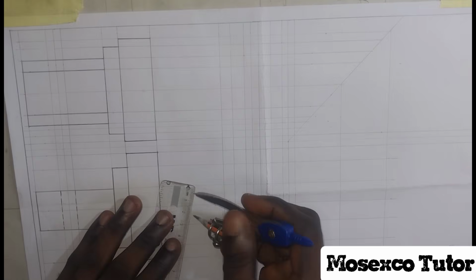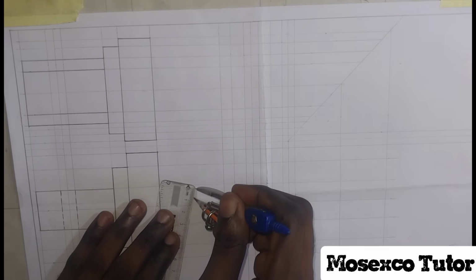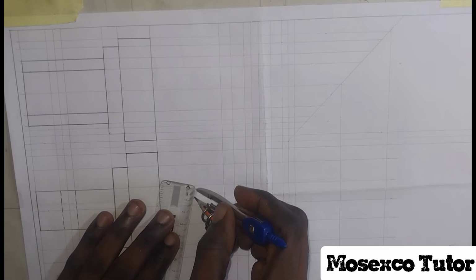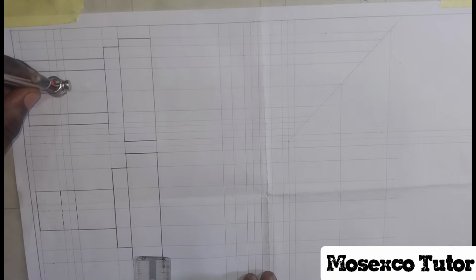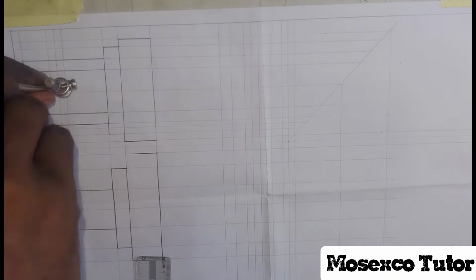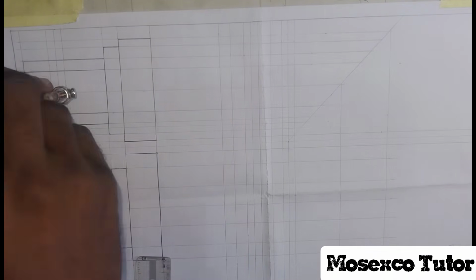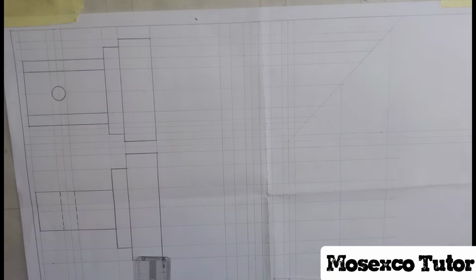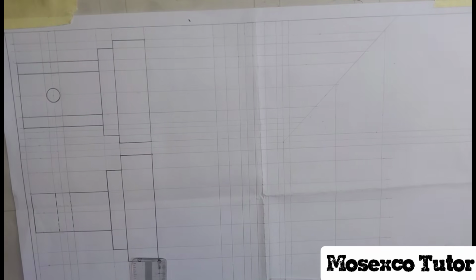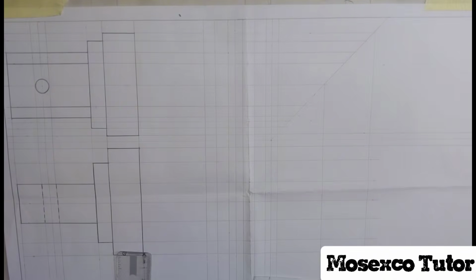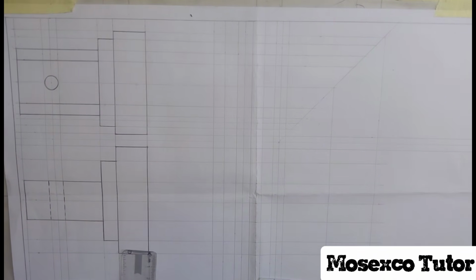But now, I proceeded to getting the circle that I have at the plan there of radius 0.6 centimeter. That's the midpoint. Then I draw my circle. So from the plan, we can see it as a circle, right? But from the front view, we can't see it as a circle. So we indicate with a broken line to show that there is a hollow part through that structure over there. So I draw my circle. Make sure your circle, when you draw it, you have just as a line, no double line. So that concludes the left-hand side of the front and the plan.